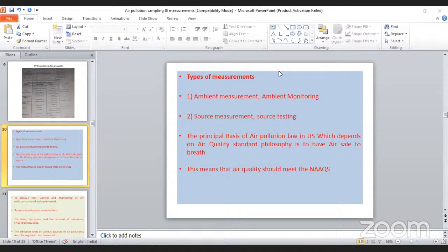For particulate matter we cannot use any sort of sensitive instrumentation like GC-MS, HPLC, chemiluminescence, spectrophotometry, though many methods are available. It is not required. So it is manual measurement followed by laboratory analysis. We can quantify that. And particulate matter measurement uses the gravimetric principle.